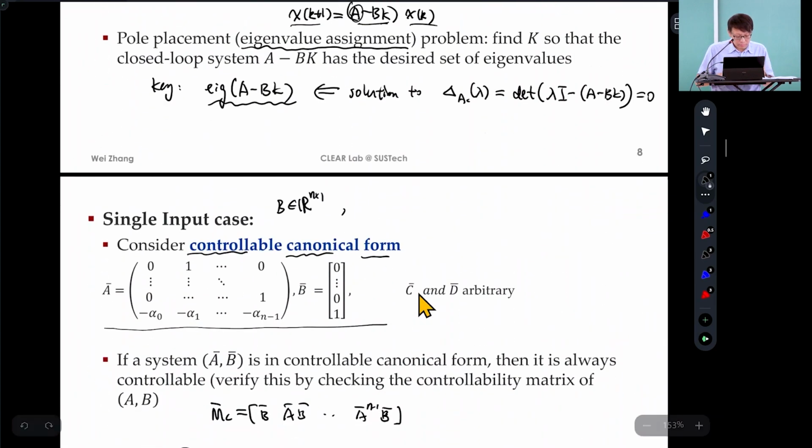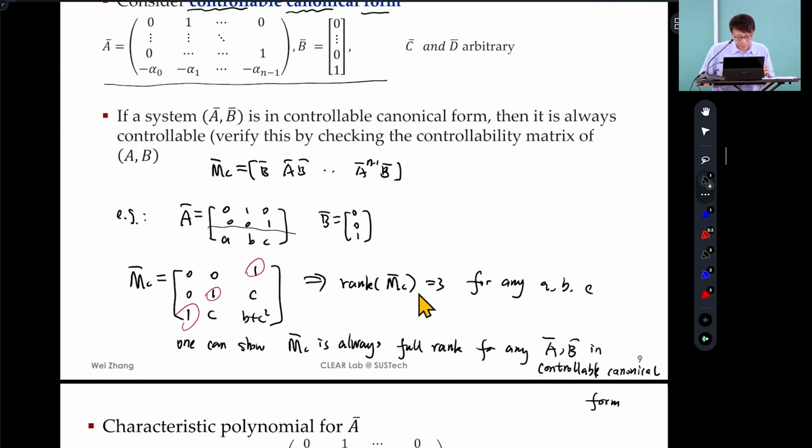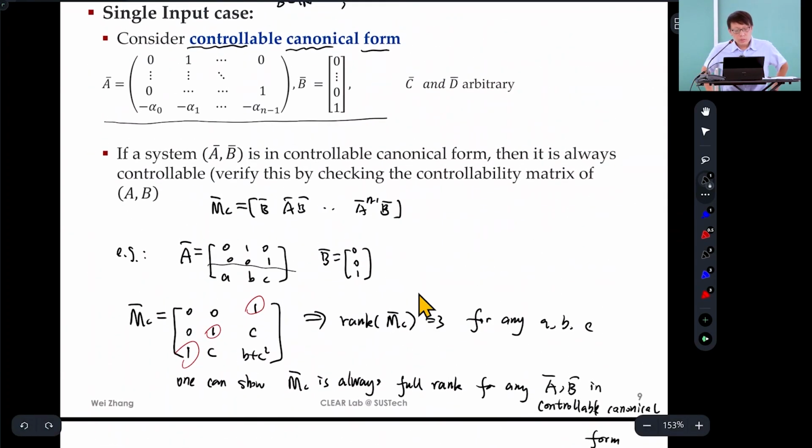I think last time we stopped roughly here. For the single input case, we can do everything by hand. At least in the midterm, I will test this. By hand, design your controller so that you can place the eigenvalues to correspond to a good response. Not tuning, not watch and see and tune, not that. Ahead of time, based on the model, you design, and you verify it works. That's what I want you to know.